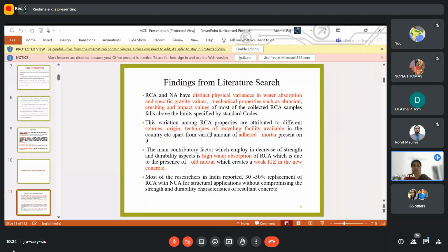And one more thing is, what happens to this recycled concrete aggregate? When I was doing my research in the beginning, I used to go in search of where there was construction and demolition activity, so that I could collect the construction and demolition waste and then manually crush it, and using a jaw crusher I could get aggregates which are 20 down, which is required for pavement quality concrete, PQC. When I'm talking about pavement quality concrete, the cement concrete slab, I need 20 down size aggregates. So I had to do some processing.